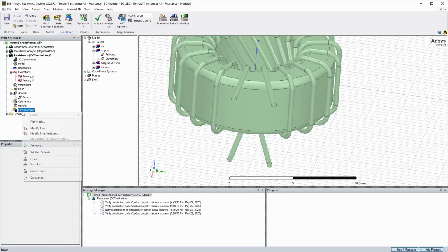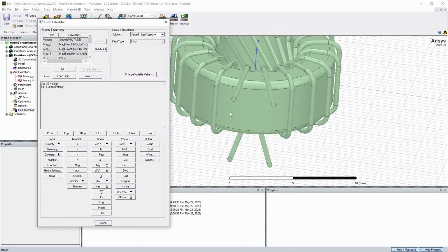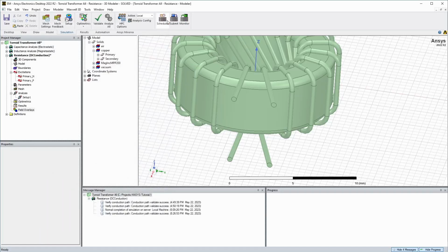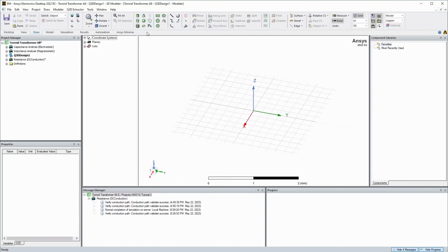So it looks like you need to do this field calculator on here to make any measurements of what the voltage and currents are here to try and calculate a resistance. And I couldn't figure out how to do it with all of these. So I could try doing a voltage across here and maybe it would be easier to figure out the current flowing through here. But I think at this point, I'm just going to go back to here and try the Q3D extractor because that's supposed to make all this stuff easier anyway. So that's it for trying to extract the parasitics manually.